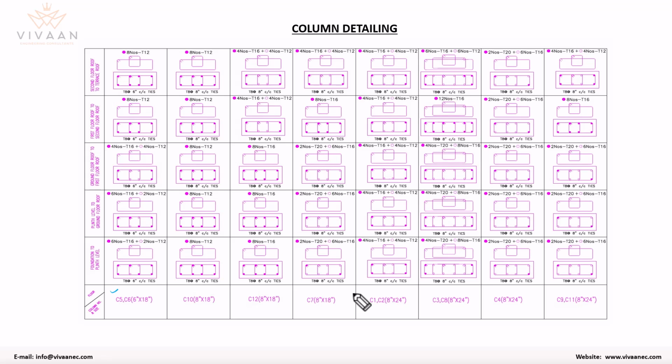Even for the draftsman, if he has multiple combinations, he needs to create detailing for each and every column. That's why most people sometimes give fewer combinations of columns. Maybe they're not doing the optimization, and although we could get a 10 to 12% deviation in the rebar sizes in the columns, maybe they'll combine them and give the higher sizes.